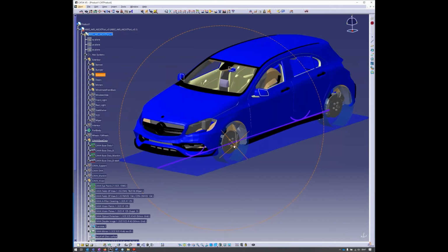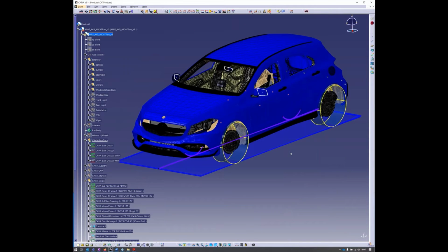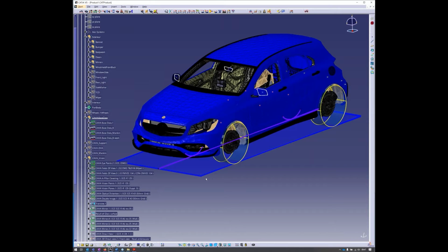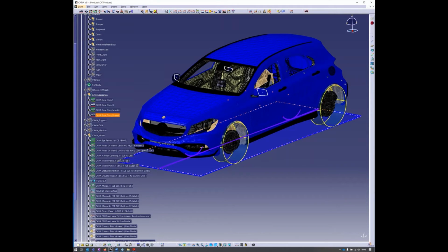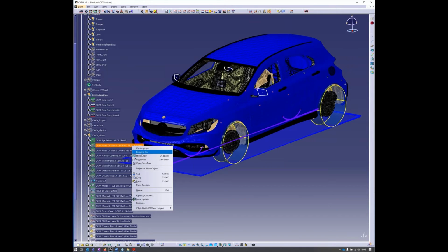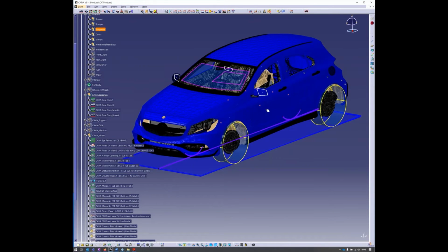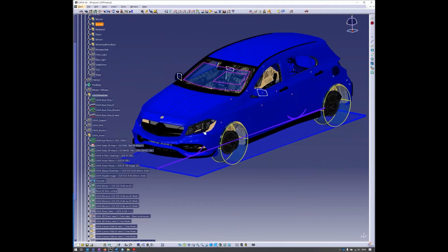The vision of the driver is regulated in several documents. For the European regulation, it's ECE R125, where there are some definitions of eye positions, but also so-called direct vision of the driver. We have other regulations also for the field of view of the driver, and I'd like to show you, for example, the fields of view calculation.